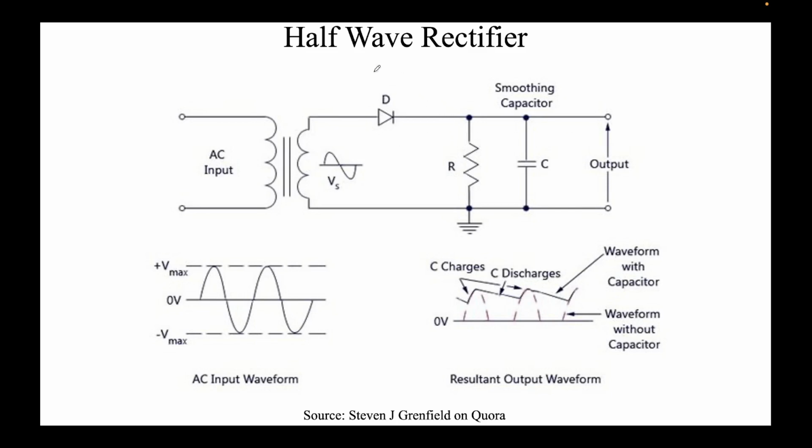It's a fairly common circuit known as the half wave rectifier. As the name suggests, on the input side we input a sinusoidal input. Like you can see, this is an AC waveform with V oscillating between Vmax and minus Vmax at a certain frequency. And this input waveform is now fed to this circuit, which has a diode, a resistor R and a capacitor C, and we measure the output across the resistor or the capacitance. You may see it either way.